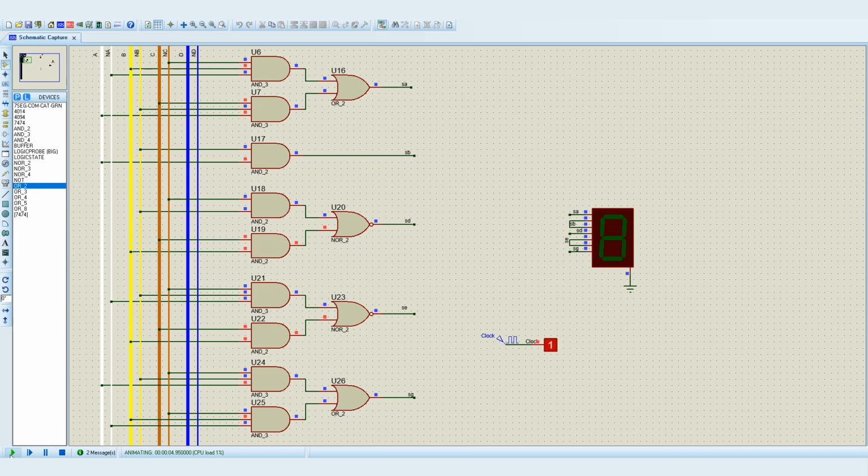But what we're going to do next is introduce a shift register delay line to have multiple 7-segment displays. We've got segments A, B, C, D, E and F, although some of them went through a NOR gate because it was not this and not that. And when you put them through an OR gate, it gives you the positive output. So these are going to our 7-segment display, and it's saying hello. So it's saying H, then E, then L and O.